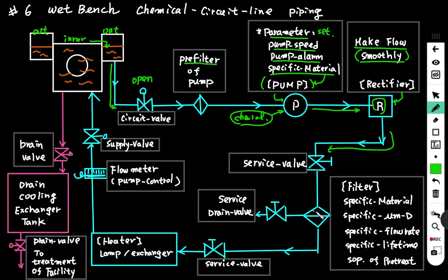And to here we have a filter, also very important. It is made of a specific material, and its purpose is just like the pump: specific chemical uses specific material. And the filter comes with a specific micron opening.